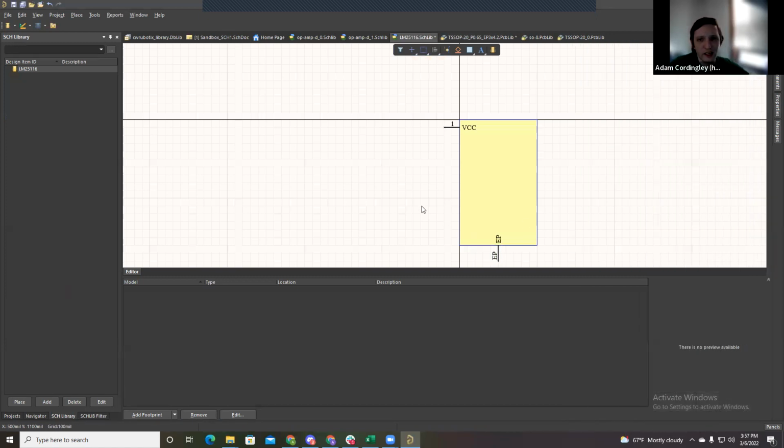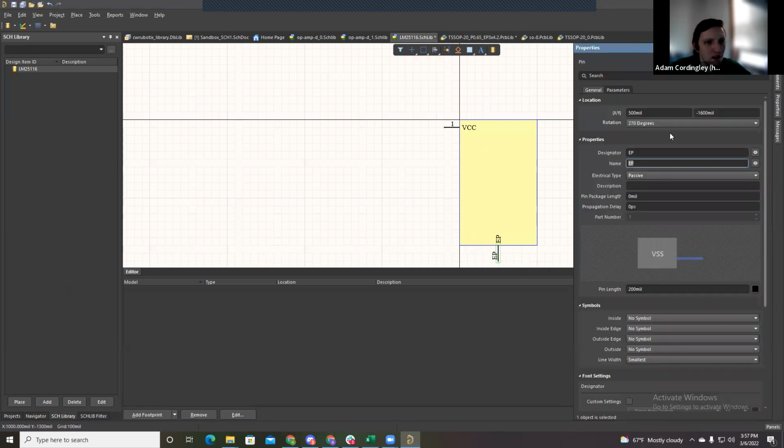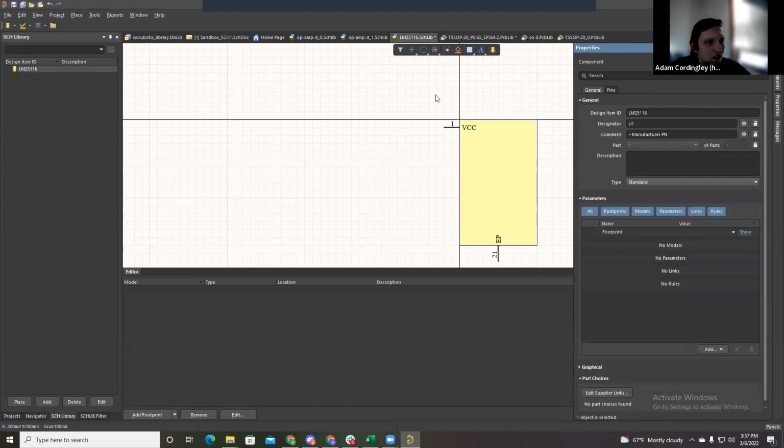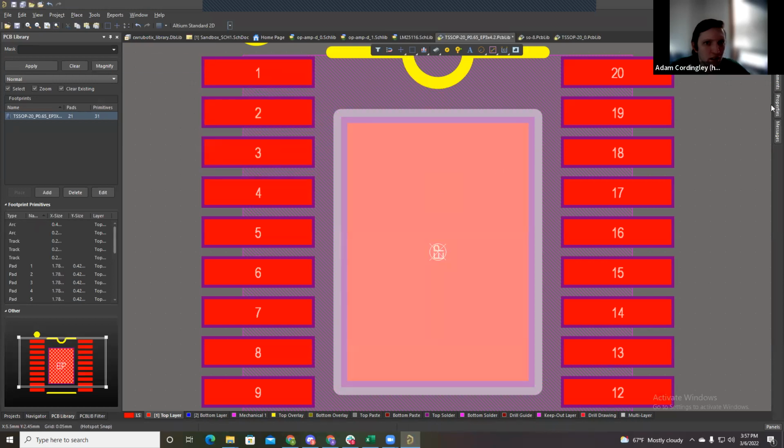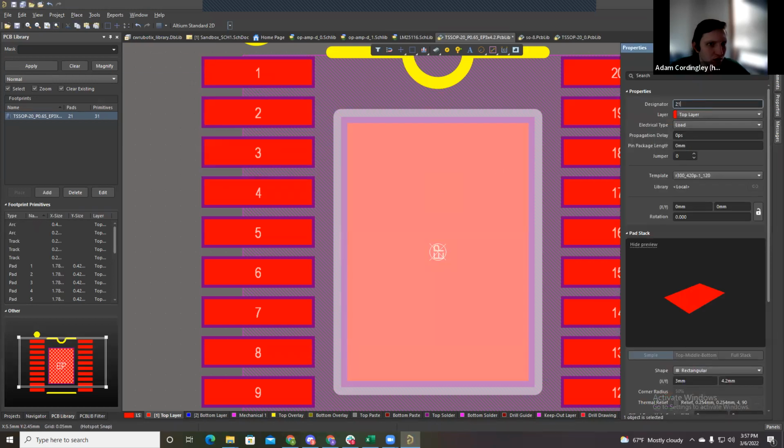That is totally legal. It's just a choice. You have to make that decision. If you want to reuse this footprint, you've got to always know that the exposed pad is called EP. So I don't prefer doing it that way. I like the numbering, so I would do the numbering and similarly give this a number 21.